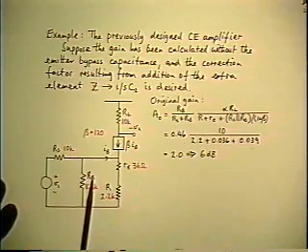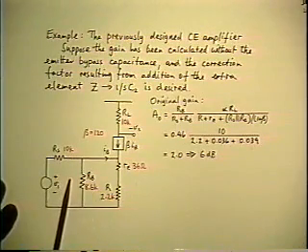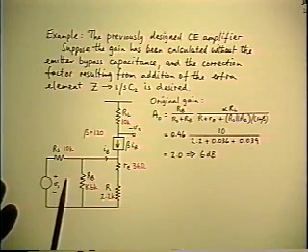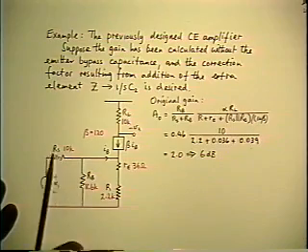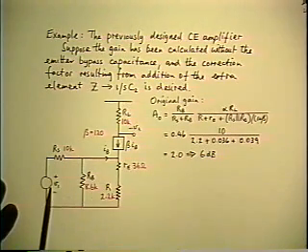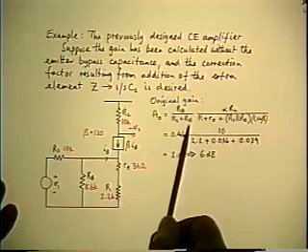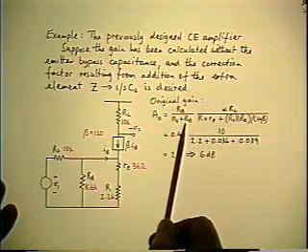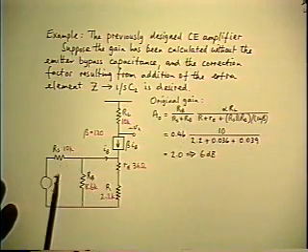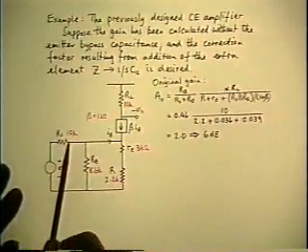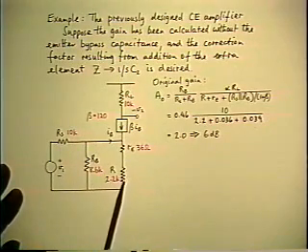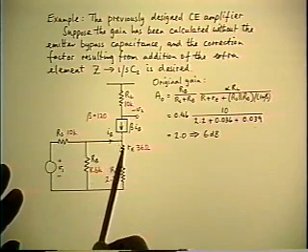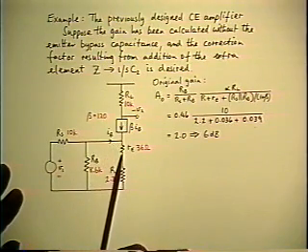So, let's take the approach of removing the first loop by Thevenin reduction. So that gets rid of the RS and RB divider directly as a multiplier on the Thevenin equivalent source voltage, so that divider will show up as a multiplier in front of the gain. Then we'll have a single loop here with RS in parallel with RB. We then reflect that into the emitter, at the same time dividing it by the ratio of the emitter to the base current, which is 1 plus beta.